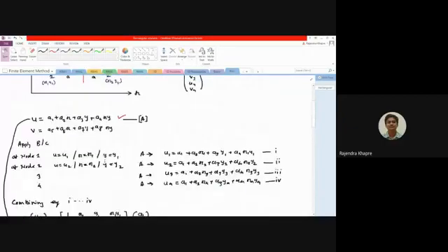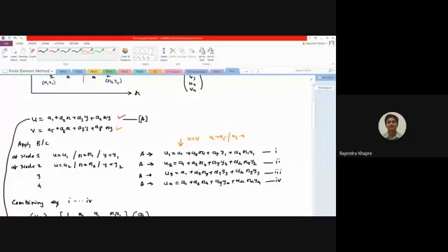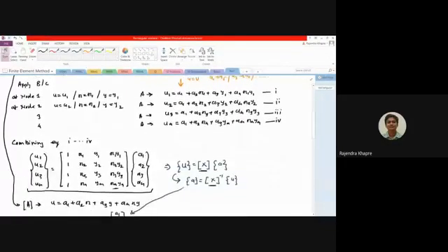So now what we have assumed is the value of u as something like a1, a2 x plus a3 y and a4 this one. Now the similar type of displacement polynomial we have assumed for v also. In this entire expression, u will be replaced by v, otherwise the rest of the elements will remain the same, that is a1 will be replaced by a5, then a2 will be replaced by a6, and so on.